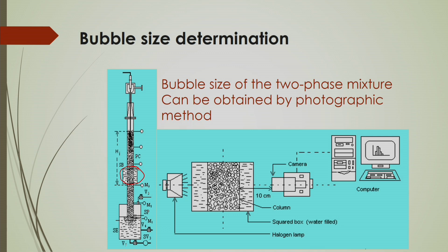Like this, if you take more than 500 bubbles manually and find their radius, the average or mean radius or mean diameter of the bubbles, then if you segregate the bubble diameters into bins or classes, within a certain range of each bubble class you can get the distribution of the bubbles with their frequency.